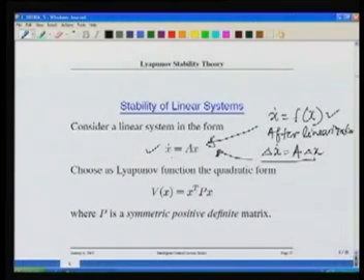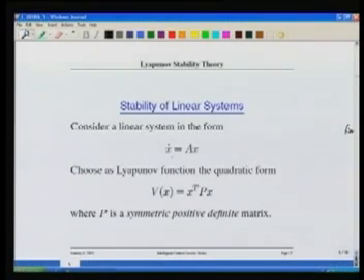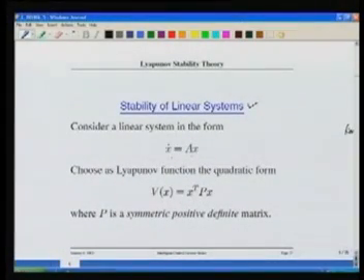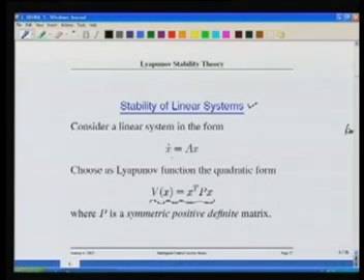And then we concluded how to determine the stability of the linearized system. We discussed in the last class the direct method and indirect method. Now, can we use this Lyapunov stability theory for stability of the linear system x dot equal to A x? The answer is yes. It is very interesting to see that for x dot equal to A x, there is a very scientific method to say what exactly a Lyapunov function is, and it turns out that the Lyapunov function is V(x) equal to x transpose P x. It is a quadratic form Lyapunov function, and this is a valid Lyapunov function. One need not ache his head to find a Lyapunov function for a linear system. It is very well defined: x transpose P x, where P is symmetric positive definite. This is very important.